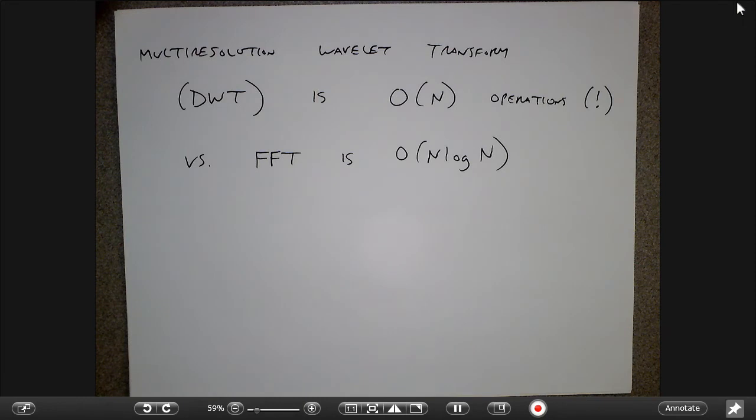And another argument for why we still might want to do wavelets is we still should be concerned about the amount of processing it takes at the receiver side to reconstruct the signal, right? So if I can reconstruct the signal with an order of n decoder as opposed to an order of n log n decoder, that will make my device much more efficient. It won't be buffering, but it will be quicker to reconstruct the signal. I'll need to buffer less because I don't need as much time to undo my processing, is one way to think about it, right?